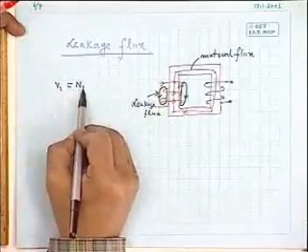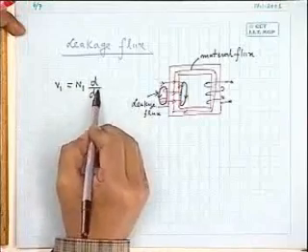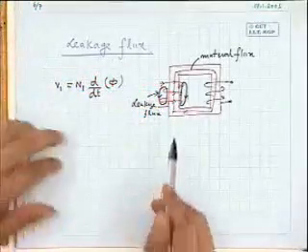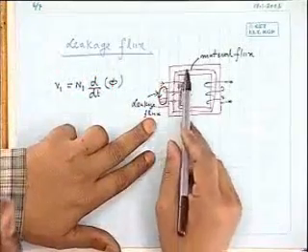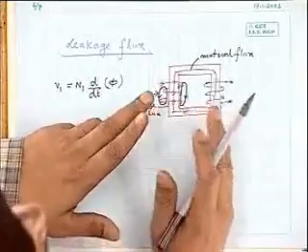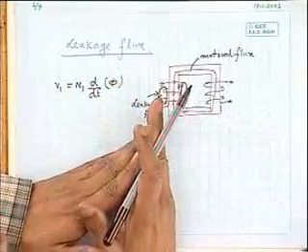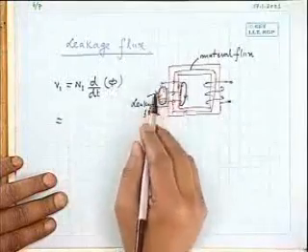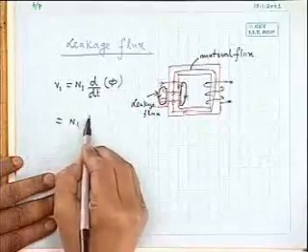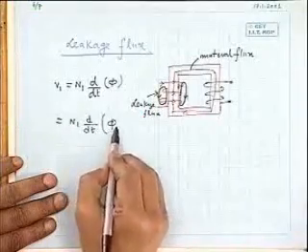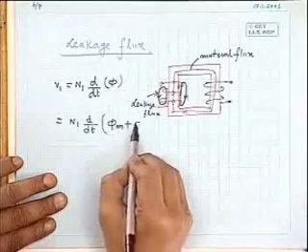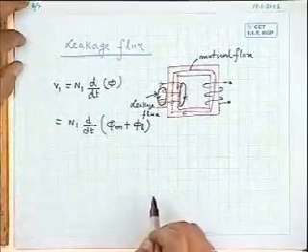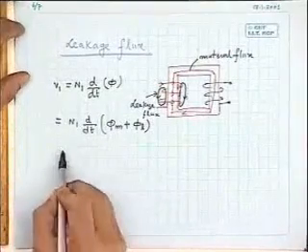Or in other words, the applied voltage, suppose this is the N1 number of turns, primary winding, is N d/dt of the total flux linking the coil. Now, while calculating the induced voltage across the coil, what flux should I take? The flux inside the core plus the leakage flux together, because both of them are linking so far as the induced voltage in the coil is concerned. So, I will now write it like this. This phi is the total flux crossing the coil. A portion of it is the mutual flux, that is the phi m. And a portion of it, I will call it leakage flux, using this small l suffix.